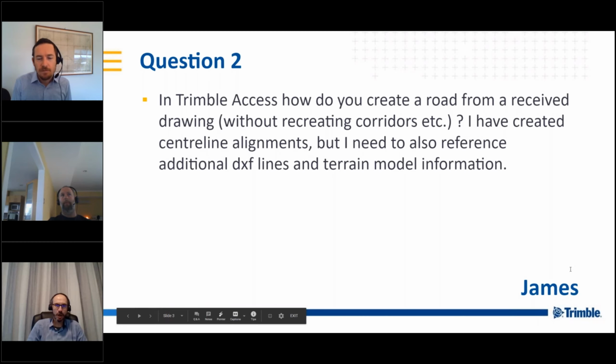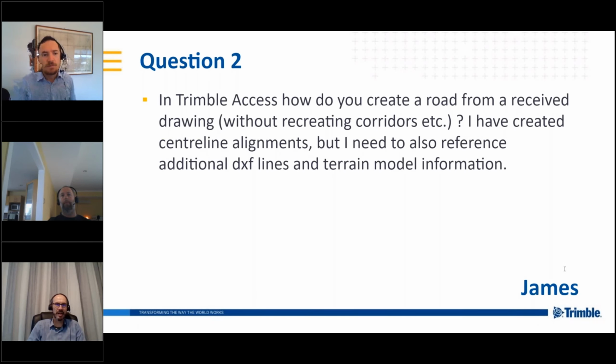Or you can copy templates too. So if you've got another RXL file, you can copy them. If you want to stake polylines, there are options in Trimble Access 2020. You can just select a polyline and stake. You don't have to create an alignment or anything. In older versions, you can select it and define an alignment out of it. Also, if you've got 3D faces in your DXF file, you can stake that as a DTM.